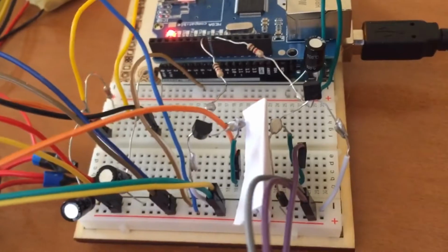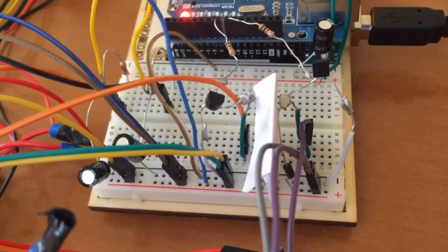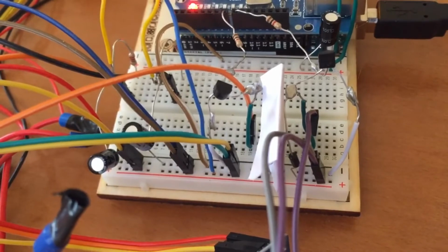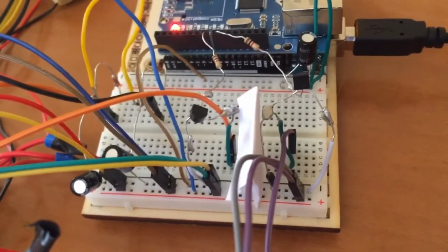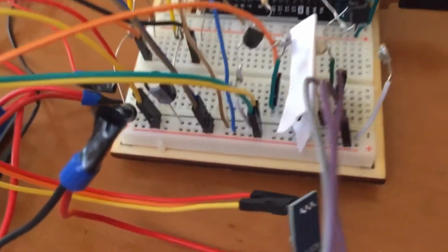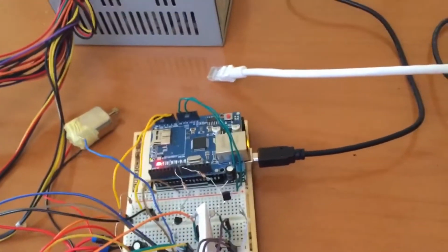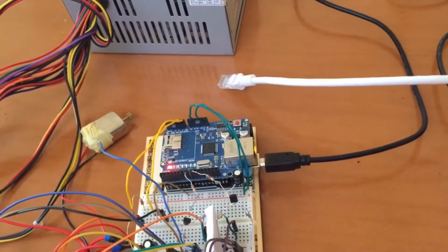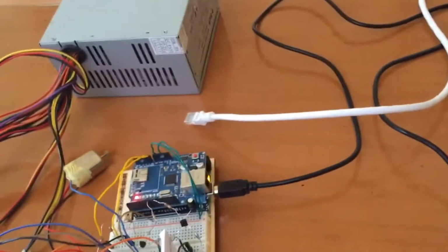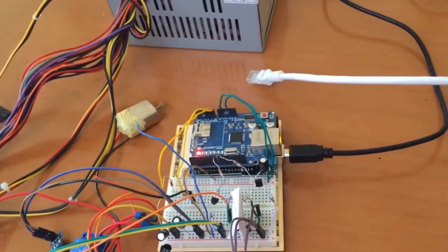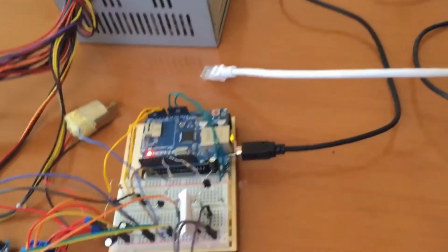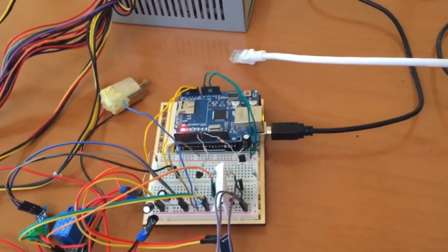This is our circuit. We are using filters and some circuits in order to reduce the noise and in order to not damage our Arduino. This is a filter capacitor across the plus minus of the Arduino. We have measured the voltage across the expected 5 volts. We found it 4.817 volt, and this is very good information. And now we can start the experiment.